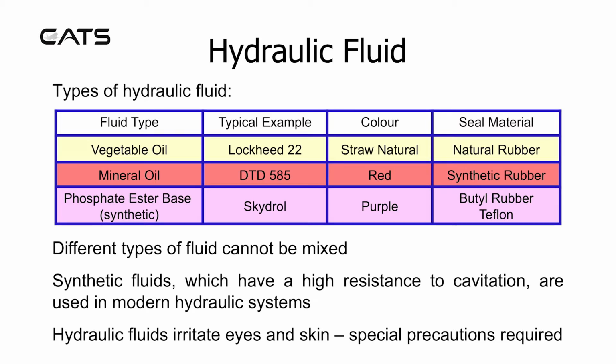Different types of fluid cannot be mixed. Synthetic fluids which have a high resistance to cavitation are used in modern hydraulic systems. Hydraulic fluids irritate eyes and skin, and special precautions are required.